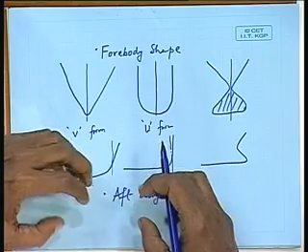If you do a bad aft body, of course, it will have penalty everywhere, but the aft body is primarily designed with flow considerations such that flow onto the propeller is good and it does not generate vibratory forces. That is how aft body is generated.